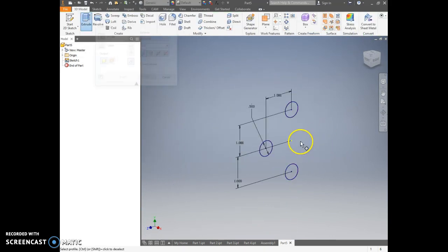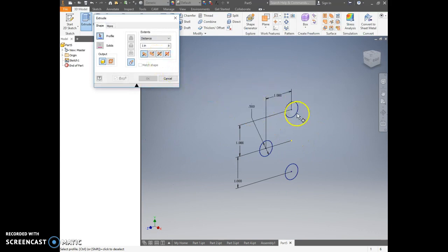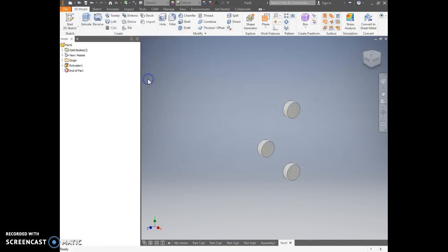And we go ahead and extrude these things. I'm going to extrude those 3 circles both ways. It doesn't tell you there on the sheet how much to extrude those, but visually looking at it, I think we're going to go 0.2 on those. And finish up with those.